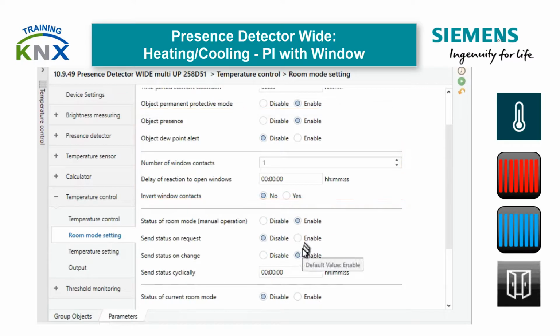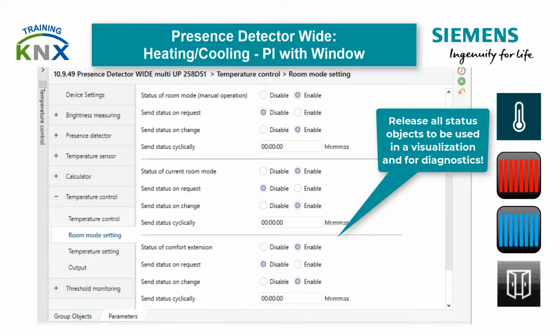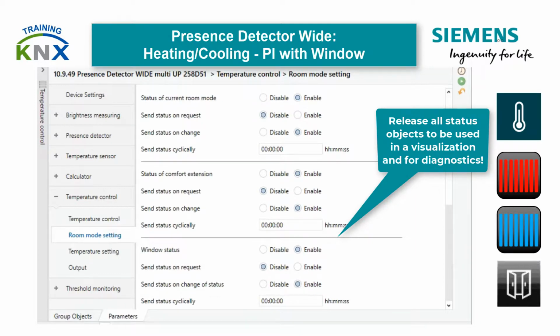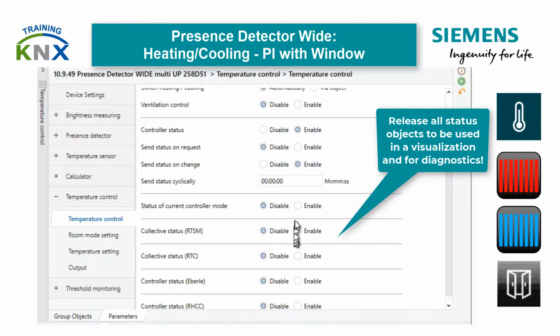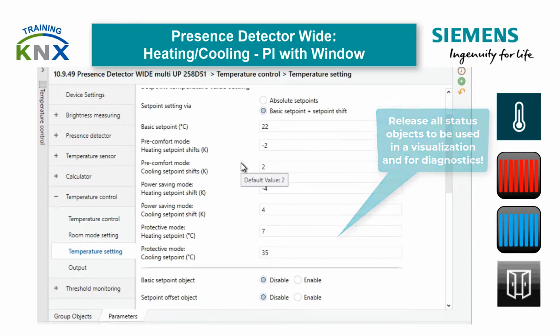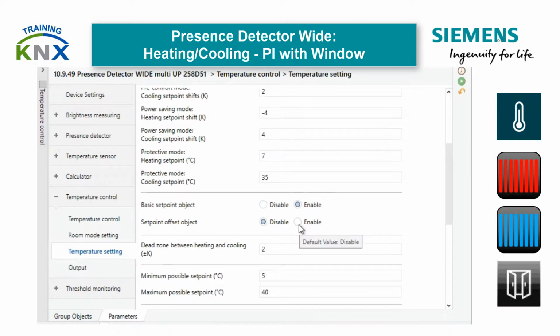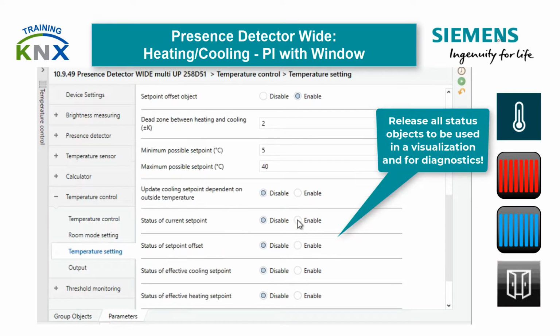There, the objects are to be enabled and the time is to be entered for the COMP4 extension. To round off the configuration, it is recommended that you activate the various status objects and also connect the controller on-off object. The latter object is self-explanatory.